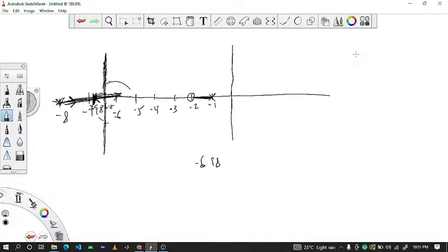And since the root locus is symmetrical, it means that there will be one zero up here and there will be one zero down here. So when they emerge at this point, when they meet and are about to break away, one of them must be asymptotic, so it goes like this, and the other one comes like this, down here and comes here.